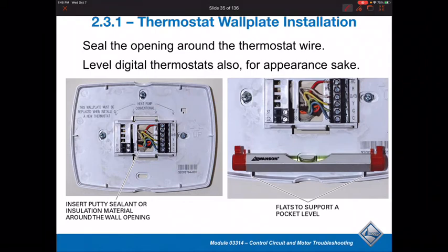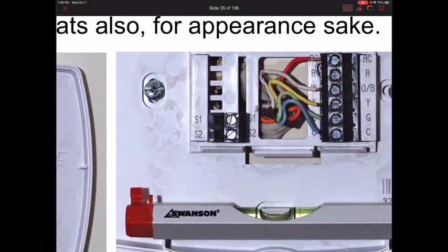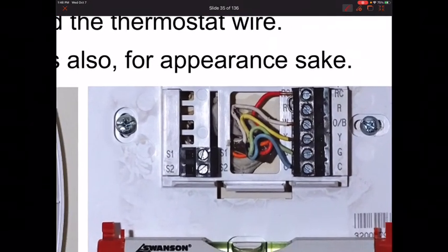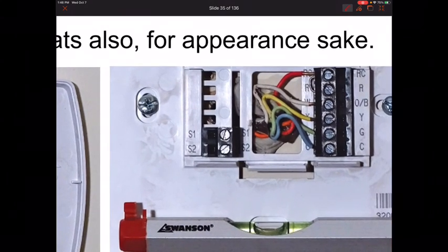Some of the things that you'll notice on the thermostats and the connections are certain designations and certain wire terminals. For example, when we look at this thermostat, this one is not necessarily installed the best, but you'll notice there's a fair amount of wire sticking out of where you put the wire in and screw it down. That's not really very good, but in the other areas, the W that's shown right here and the Y, notice how they're much shorter.